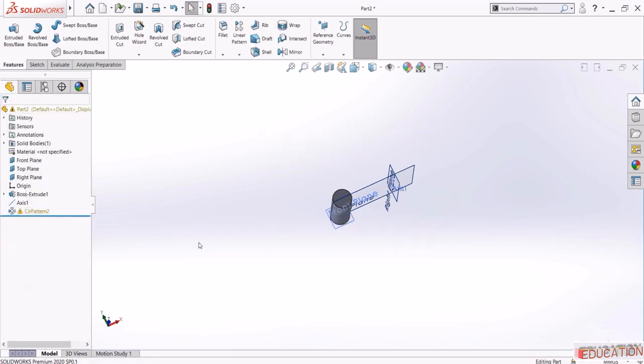And the reason why we have an error message is that these bodies will not be connected. So how can SolidWorks see them as one body? If we have a base here and they are connected to it, then there is no problem in patterning a feature. But now, if we pattern a feature like this, nothing will hold it, or nothing will connect it to the other features, and that's why you will have 9 features not connected, and in the end, they will form one body, which is impossible.